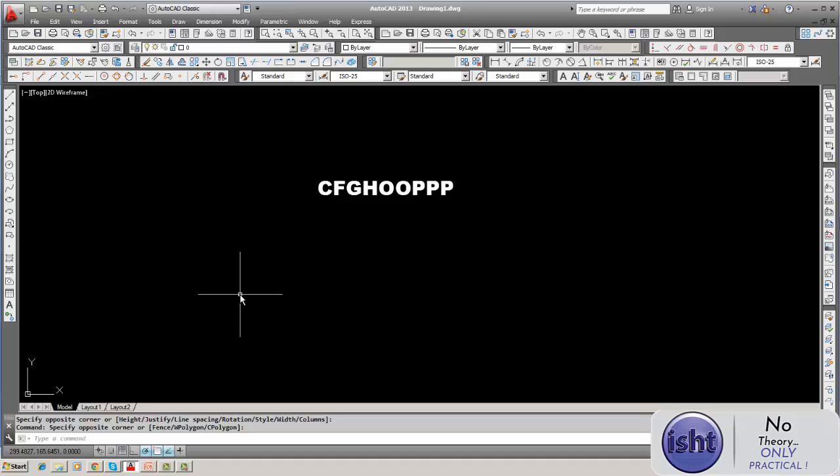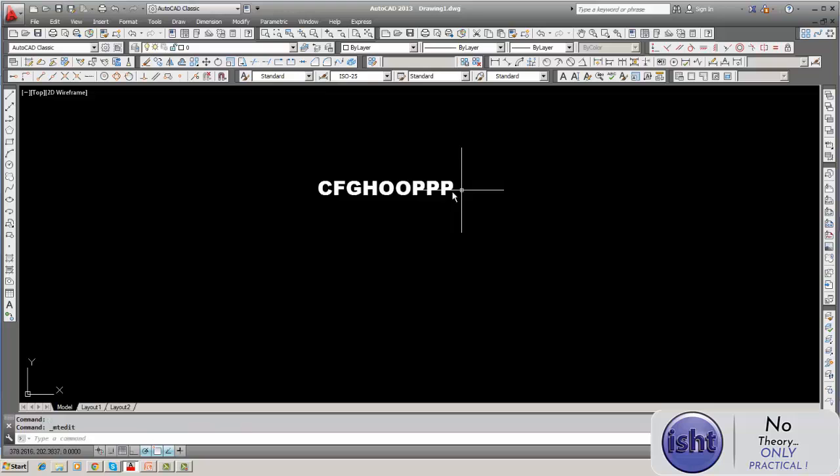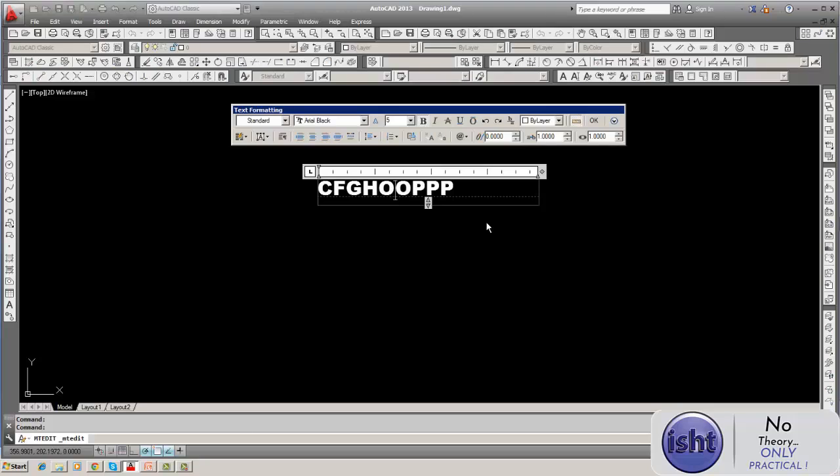that is 200 mm, 100 mm. Then you have to reduce the scale. Suppose you have typed the letters at 5 mm height. What is going to happen, since they are all on the same drawing, the text matter also will be reduced to 1/10, that is 5 mm becomes 0.5. So when you actually take a print, the drawing will be to a 1/10 size, but the text matter also will be 1/10 size. 0.5 mm we cannot read, it is so small.